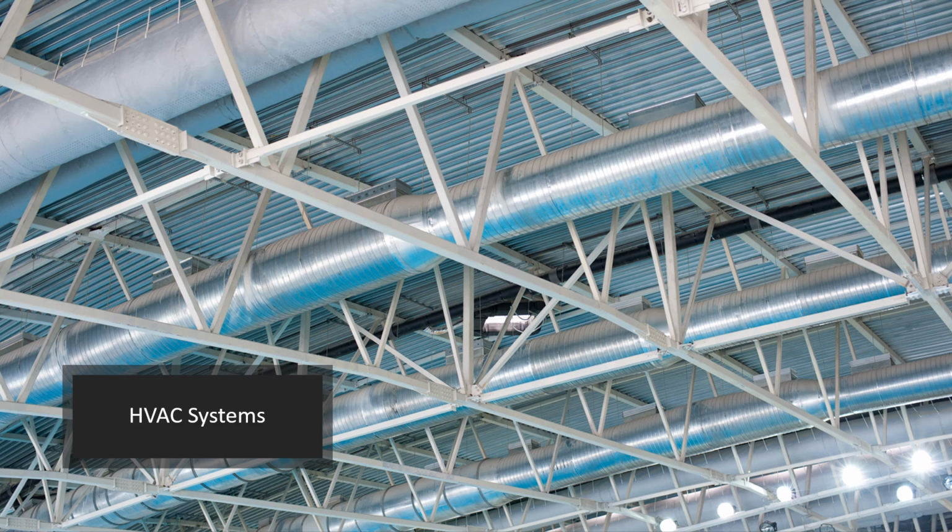by exchanging heat or energy between exhaust and incoming air, thereby reducing the workload on your HVAC system. Implementing zoning can also help minimize energy waste by conditioning only occupied areas of the facility. Your control systems are typically your building management systems, or BMS, a centralized control system that is used to monitor and control the HVAC systems across the facility. It can adjust temperatures, humidity levels, and airflow based on occupancy or time of day, improving comfort and energy use.